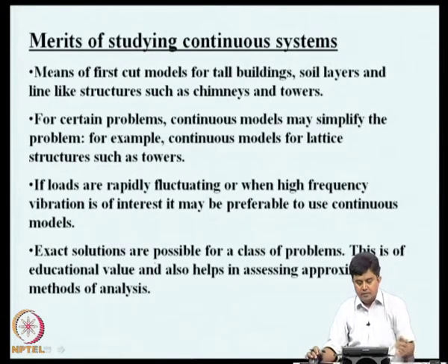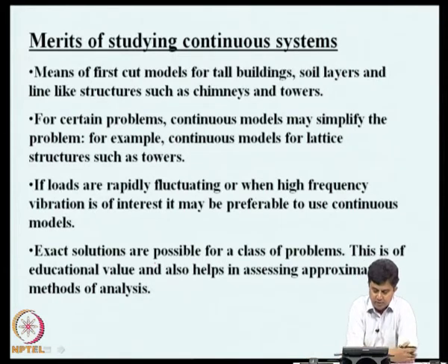So, we can make some concluding remarks on vibration of continuous systems. Why do we study continuous systems? They serve as means of first cut models for a class of structures like tall buildings, soil layers and line-like structures such as chimneys and towers. So, in their own standing they have certain worth.